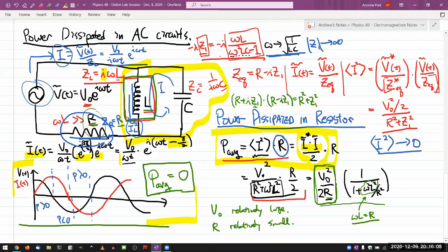And this is the principle or reason behind power factor correction. If you have an inductive load, we are used to saying large inductive load. And I think by large inductive load, we really mean a kind of inductive load that would draw large current. And sometimes it actually means low L. So if you have a large inductive load, without this corrective capacitor here, a lot of the current will be forced to go through, let's say, the resistance of the power transmission line, and you'll be wasting a lot of power.